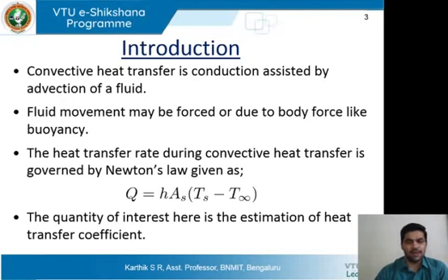Now, in any convective heat transfer problem, the motive for solving such a problem is to estimate the value of the heat transfer coefficient. One will be interested to know what the value of this heat transfer coefficient is. As you can clearly see from Newton's law, the value of the heat transfer coefficient dictates the heat transfer rate.